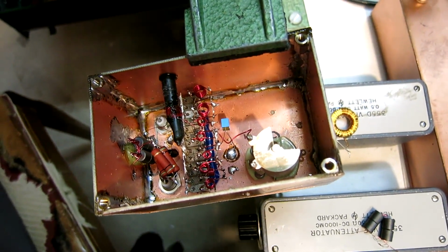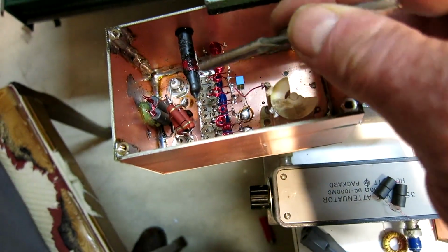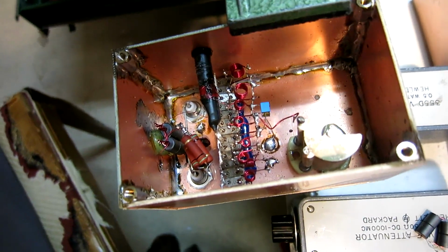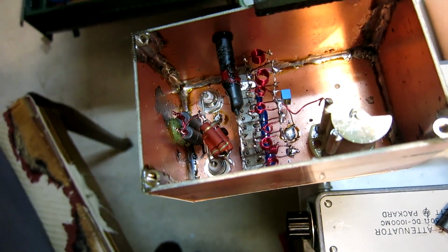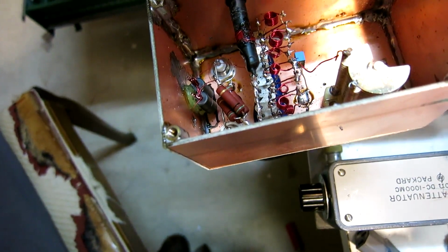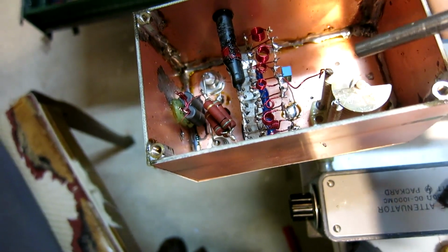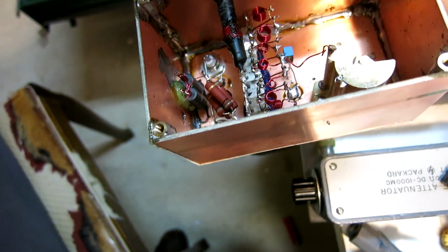Here is the selective load for 10 megahertz. There are 13 crystals here, some of them with coils of different size to make them have the series resonance at the same frequency. And then they are tuned with a fixed capacitor here, 200 pF, and this variable capacitor. And then on the other side they are fed with 450 ohms from this 3-to-1 turn transformer.